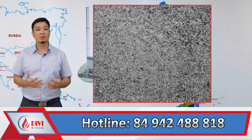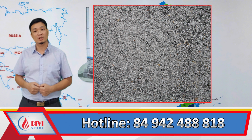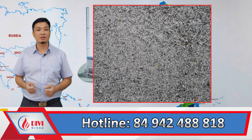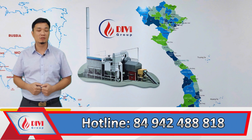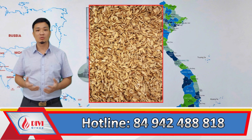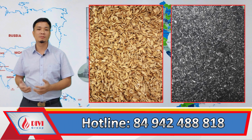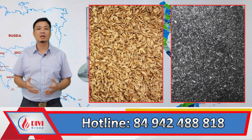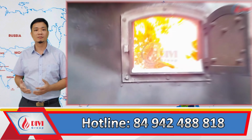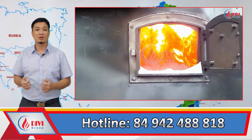For fuels with stable ash content and particle size similar to or suitable for the air velocity or fluidizing air force, the ash itself can be used as the fluidized bed material. A specific example is rice husks, which have a stable ash content of 20% to 25%, with evenly sized and lightweight ash particles. If the primary air supply system is properly designed, rice husk ash can serve as the fluidized bed in a rice husk-fired fluidized bed boiler. The video you're watching shows the fluidization process of a fluidized bed boiler burning rice husk.